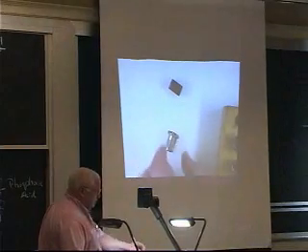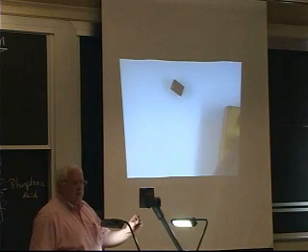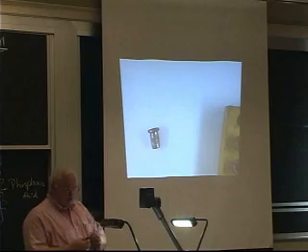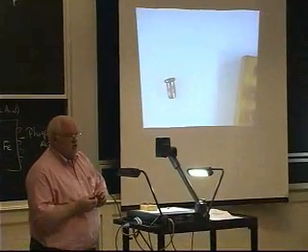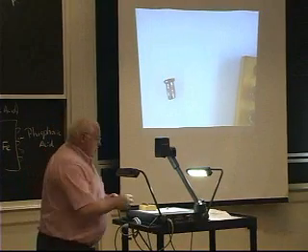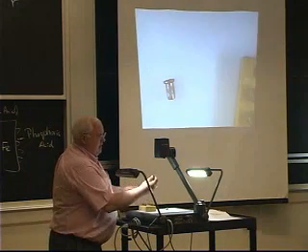If anyone's put some cheap wood furniture together at home, this actually happens to be a knurled piece that has threads on the inside. I'll pass it around. It's zinc plated now. To make this part, you start off with 3/8 inch rod. You shear it into a known length, and this was phosphated. You might feel a little bit of soapiness on the surface because they then use a stearate, basically a soap, as the lubricant. And what they wanted to do is they would first take this guy, which is a sheared end.